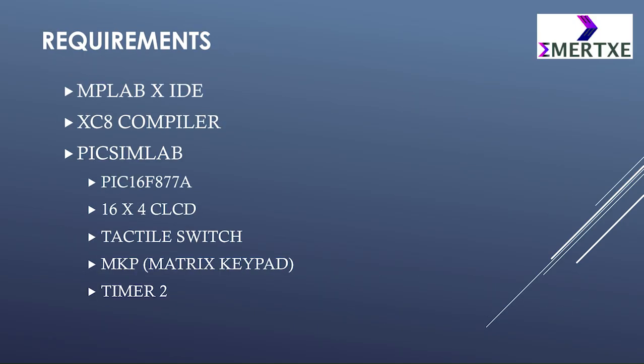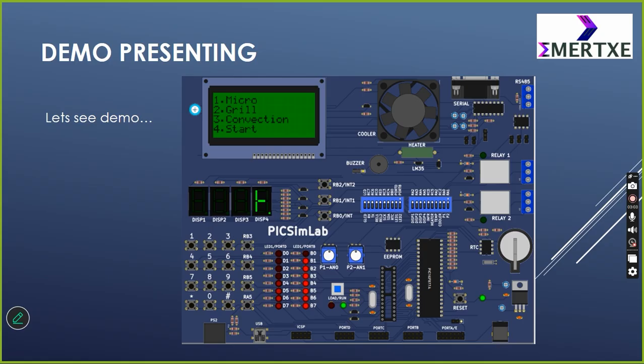The entire system was developed with embedded C using the MPLAB X IDE. Since we were working with a simulation environment, PICSimLab allowed us to verify our code on a virtual PICGenios board, ensuring that our register configurations for keypad and LCD were industrially accurate. We used the XC8 compiler in MPLAB. Let's see the demo of our project.